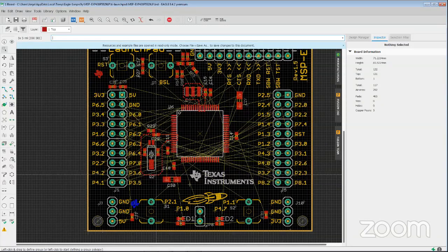But now if you start dealing with high power, high current, if you have sensitive signals, if you're doing anything medical, if you're doing anything related to RF in any way, shape, or form, Wi-Fi, Internet of Things, if you're doing USB, especially the 2.0 and 3.0 standards of that protocol. So, anything like that, the Autorouter is just not the tool to do it.